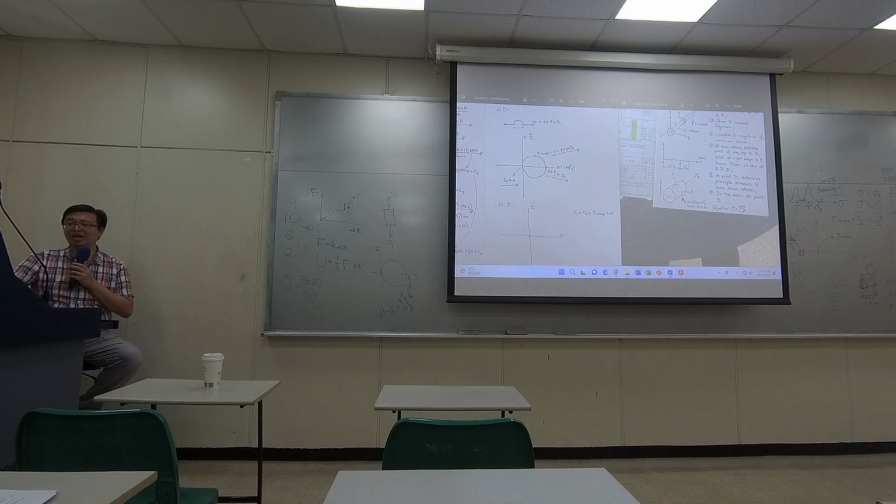And at point E, like I said, it's on the neutral plane. There's no stress, so the Mohr circle is like a dot. No stress, so the principal stress and the maximum shear are all zero at that particular point, because there's no stress over there. Okay? So, any questions about the analysis right here?